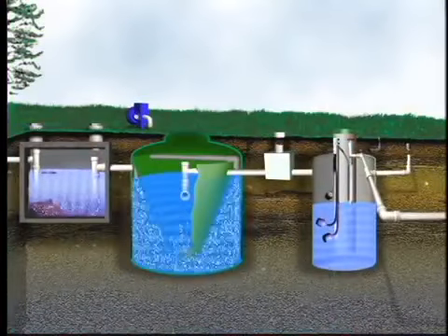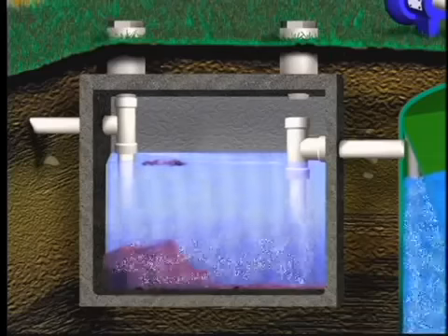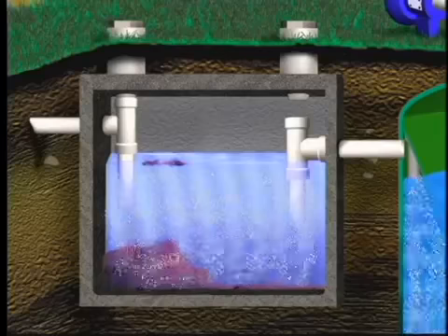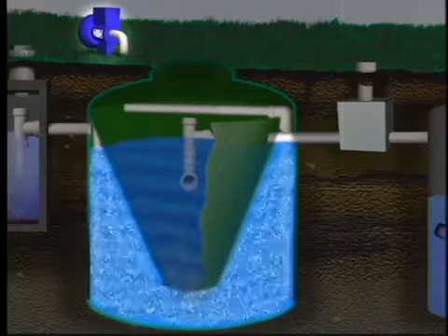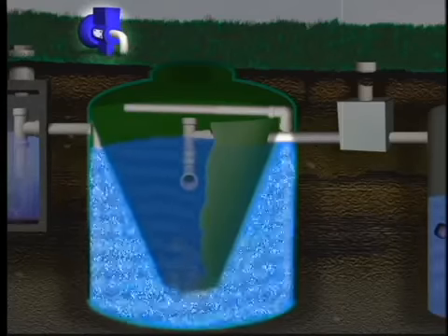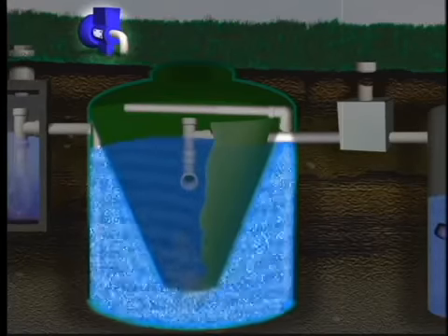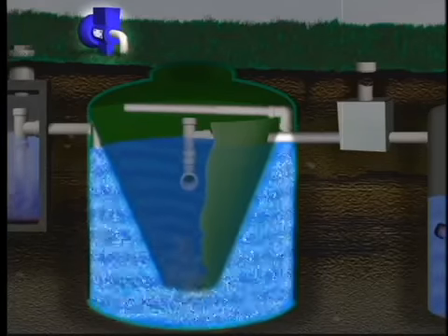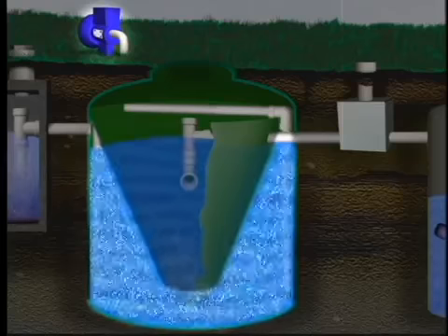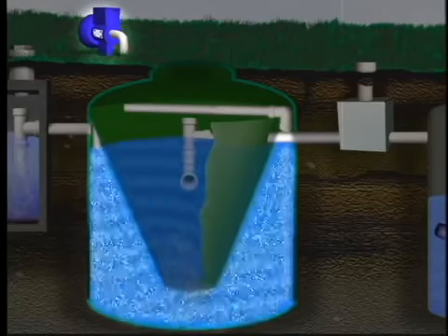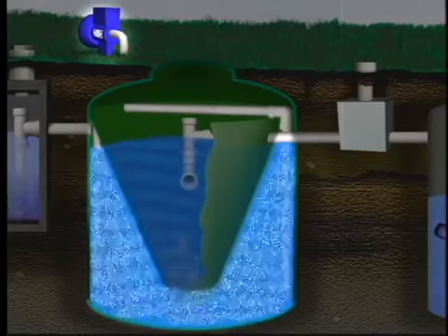The aerobic treatment process contains four main components. The first is a permanent tank, generally referred to as the trash tank. This stage removes materials that microbes cannot degrade. Second is an aeration chamber. Treatment in the aeration chamber is a biological process. The air supplied by the air pump allows microbes to thrive. The microbes consume the waste, transforming it into a non-polluting cell mass, non-degradable material, and gases. The chamber contains an aeration system including an air pump, piping, and diffusers to force air in.